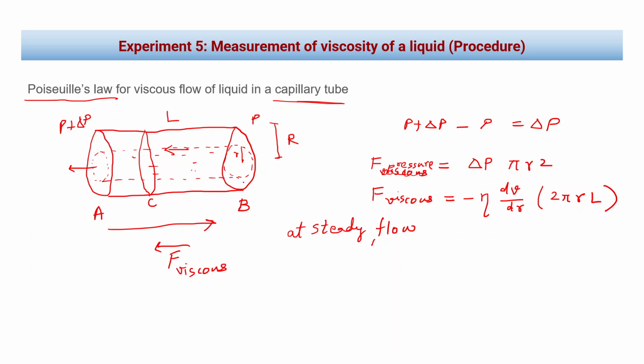So when flow of fluid is in such a way, then it's called steady flow. When the flow is steady, this happens when all the forces acting together are zero. That means it's flowing with a constant velocity, because we know force is mass times acceleration, and if I'm saying force is zero, that means acceleration is zero. Acceleration is what? Derivative of velocity, right? So if derivative of velocity is zero, means velocity is constant.